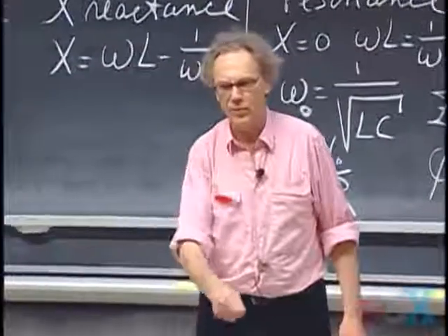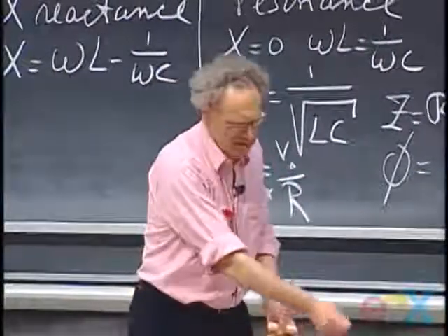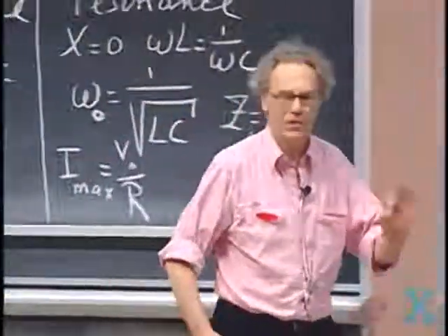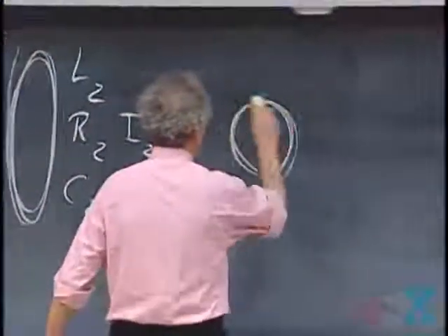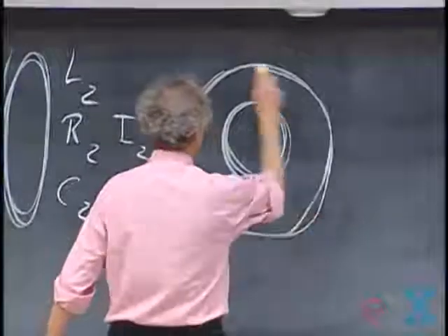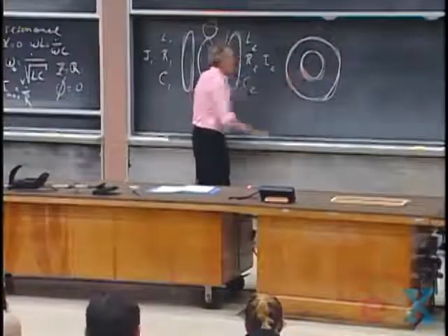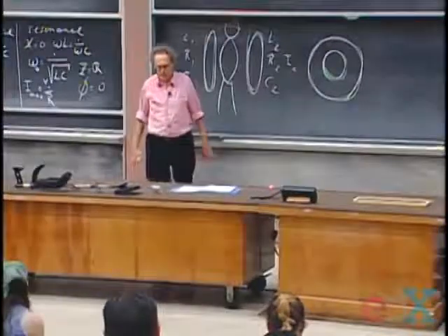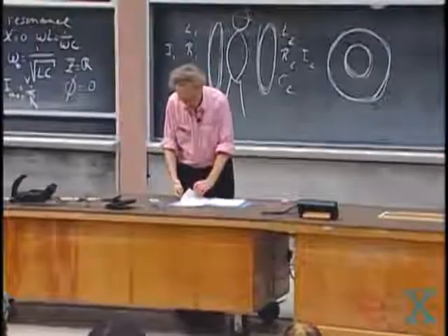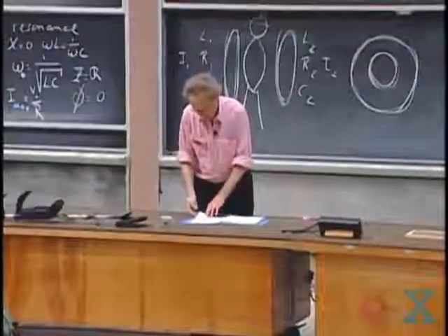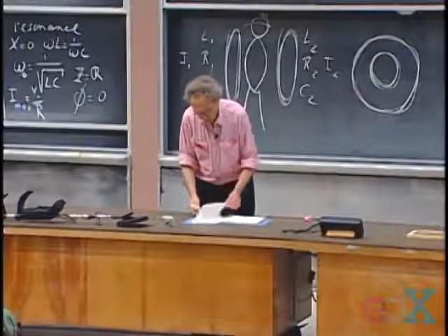When I was a kid, I went often to the beach in the Netherlands, and there were often people who had these metal detectors, looking for coins. And those metal detectors, basically the same idea, always two coils. When metal comes nearby, you have a system that goes off resonance, you get a difference in magnetic coupling between the two coils, and the system goes into alarm.